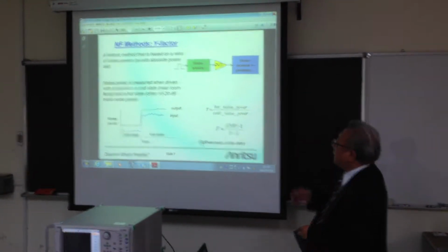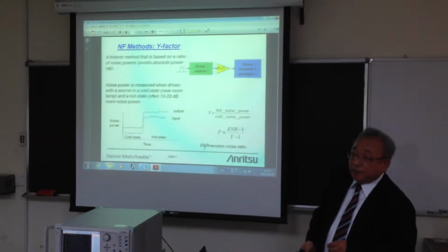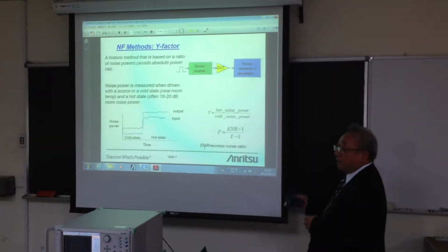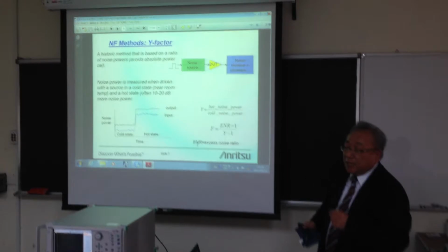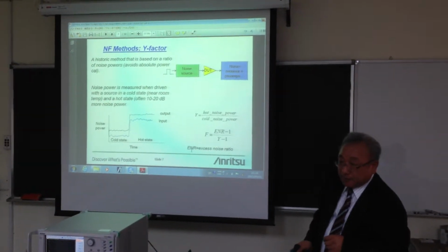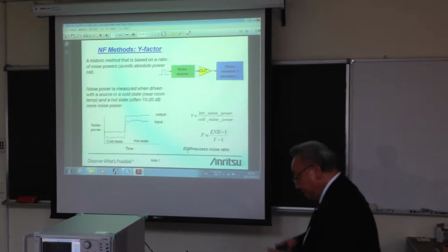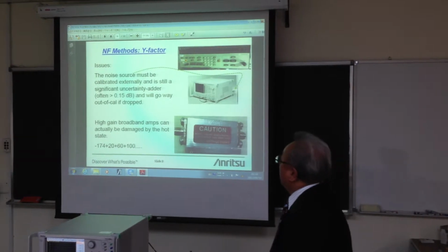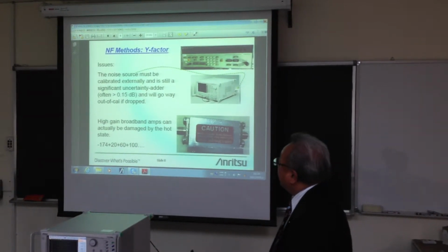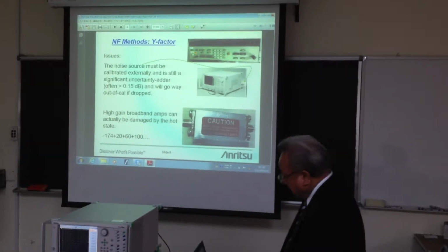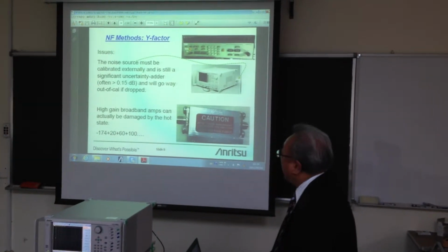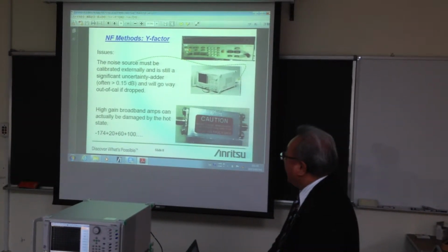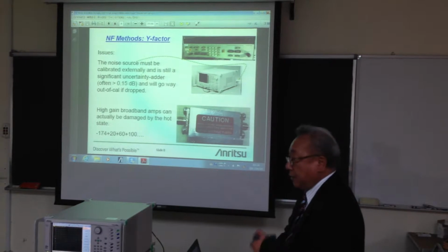But that kind of calibration is very difficult. So it is available only at limited calibration metrology centers. So that is the Y factor measurement method. It is used in a noise figure analyzer, and some VNAs can also use the noise source.